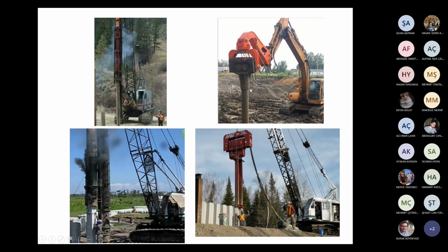Vibratory hammers are attached to the top of the pile. And these two are vibratory motors, oscillation motors. These vibratory drivers are used for pile driving and also sheet pile installation and removal as well. Sheet pile, a special kind of pile.